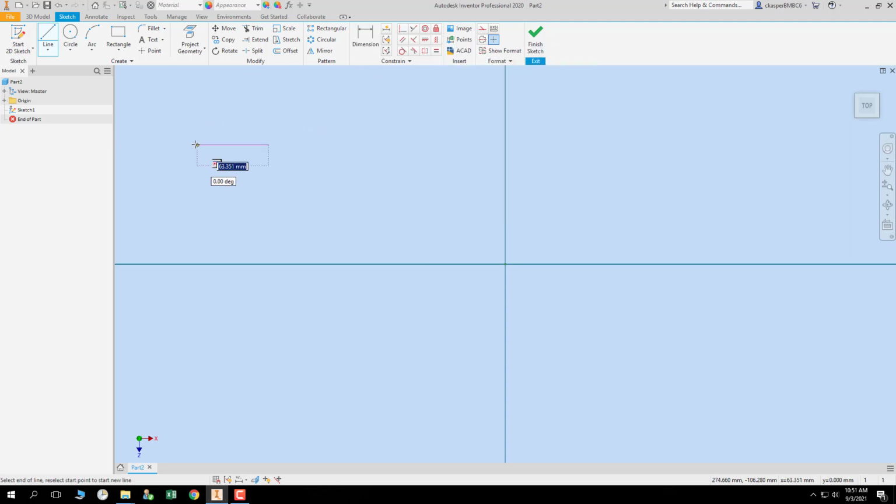And what that means is, when I have this line like this, notice it kind of locks or sticks into that straight across mode, and that gray icon appears, that gray with the red. If I were to click that right there, that would constrain that horizontal, and constrain means locked into.